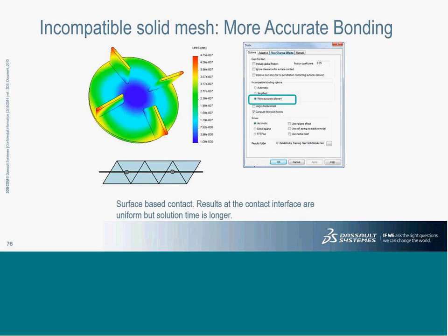If you go to the properties of this study, you find something called the more accurate bonding option. Frankly, even though it has been included in the training manual, for understanding, I would suggest not to worry too much about it. You can leave it at the automatic setting and the software decides it. But if this particular option is selected, then if you see the image below,